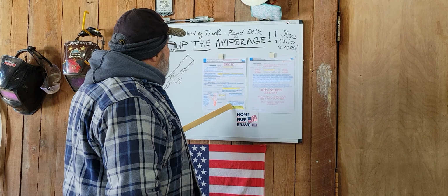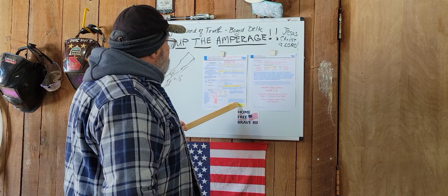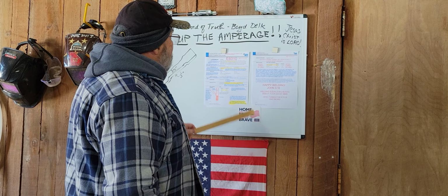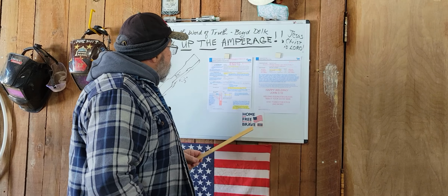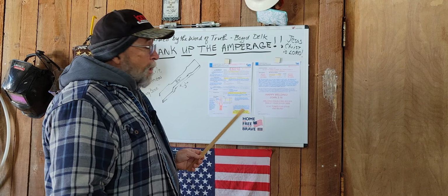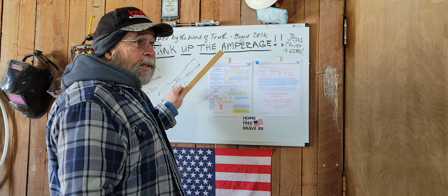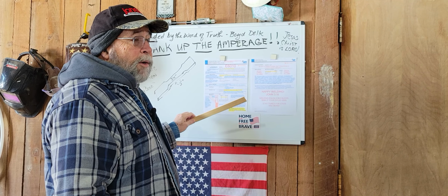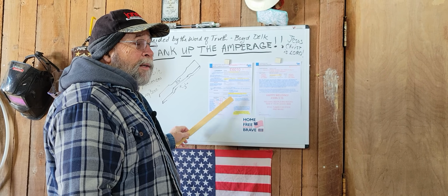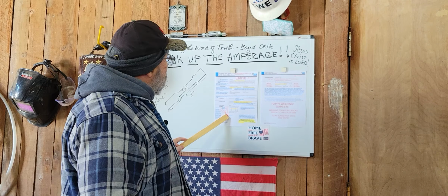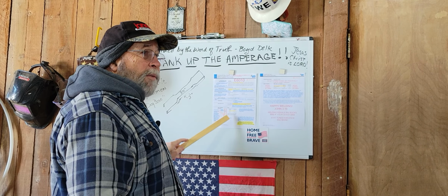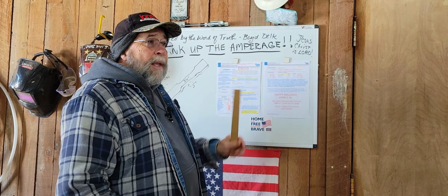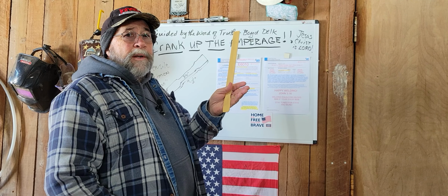So this enables running a slower travel speed while improving maintenance of the arc at lower amperage, with less sticking of the electrode. I hope this has been helpful. As I said, I will in the near future have plates and do actual welding videos on the root pass, open butt, so you can see exactly what I'm talking about when I say carving the walls. If you carve that wall on an open butt, that's your penetration right there.